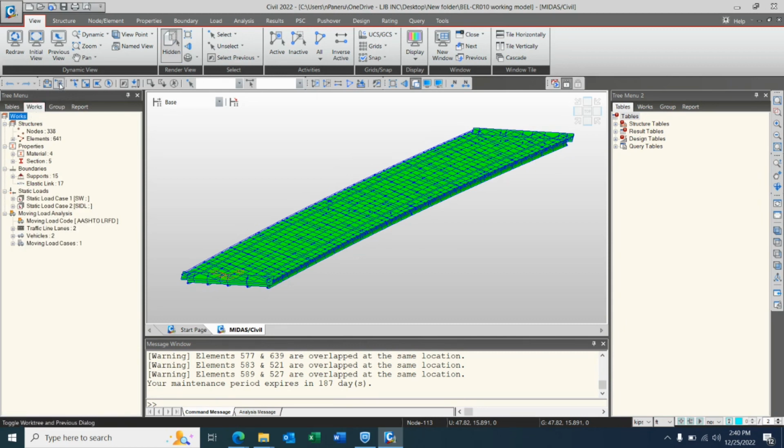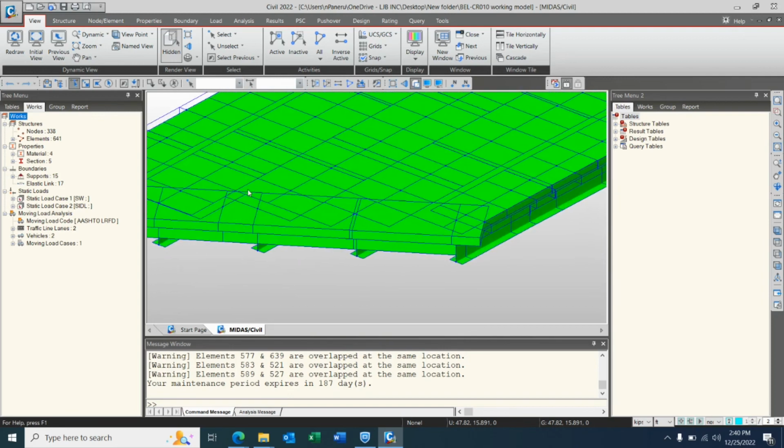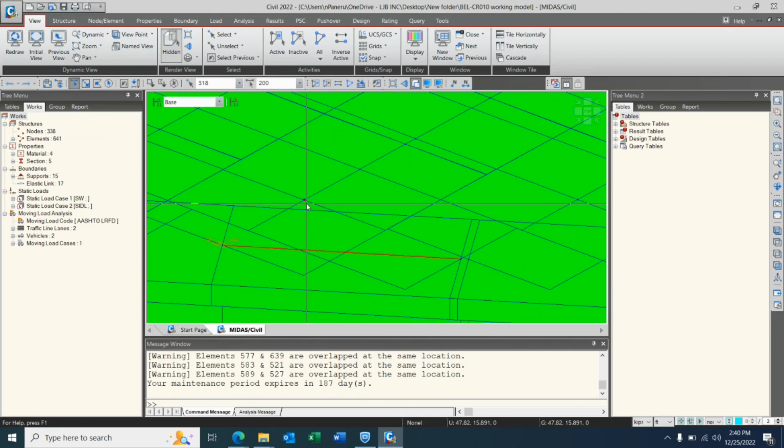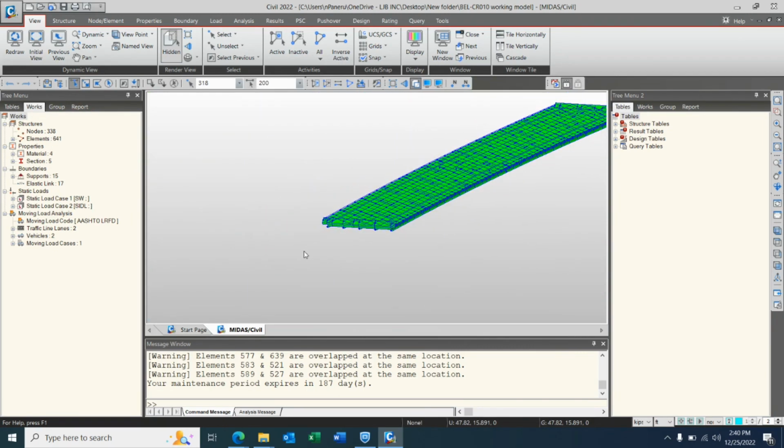You can just click here or select this option, and this is used to select a node or an element. So if you click on that and come here, select a member, I can select a member, or by clicking on node I can select a node as well. For any of these tools, if you want to activate them, you just click once, and if you click again, it will deactivate. Sometimes you may get confused about how to get rid of a tool. Then you can just come back and click on the same icon.